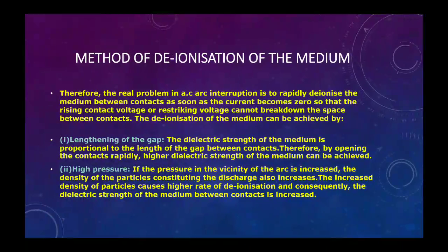The dielectric strength of the medium is proportional to the length of the gap. If the gap is increased, then the dielectric strength is also increased. Therefore, by opening the contacts rapidly, higher dielectric strength of the medium can be achieved. So the deionization can be achieved.